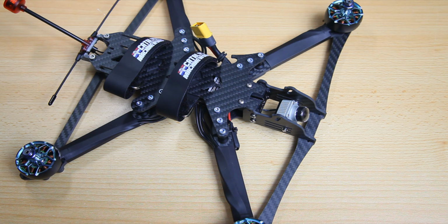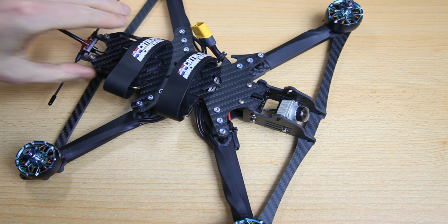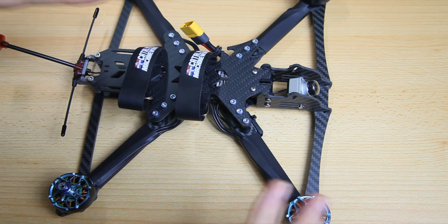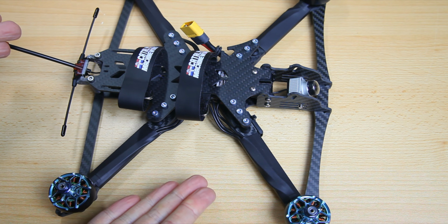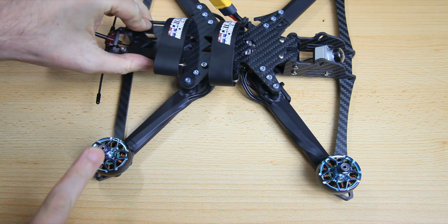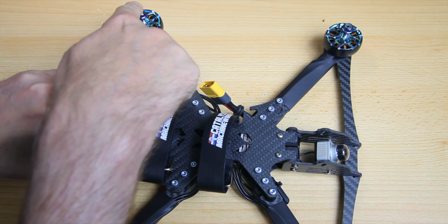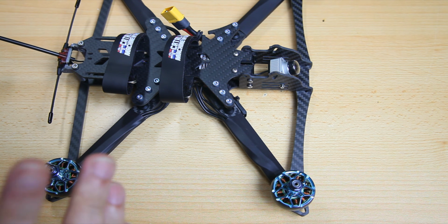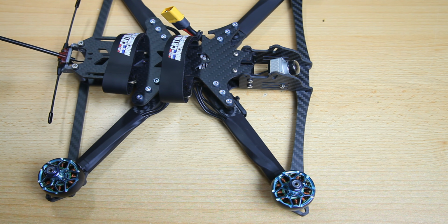Thank you very much for tuning in, and this will be a short instruction video on how to change the motor order in BetaFlight. So I've just finished building this quadcopter, and BetaFlight now thinks that this is motor 1, this is motor 2, this is motor 3 and this is motor 4. However, it is not. See, I've changed the orientation of my 4-in-1 ESC. And therefore the motor order is incorrect.